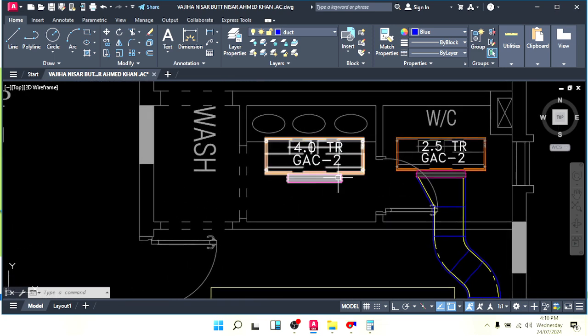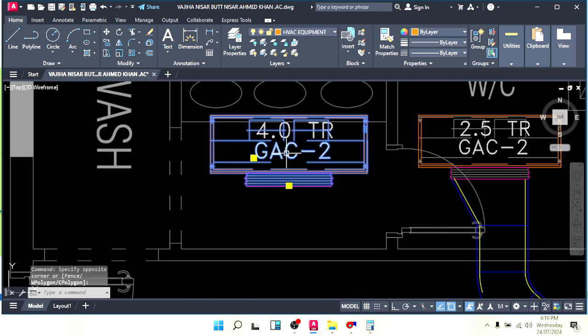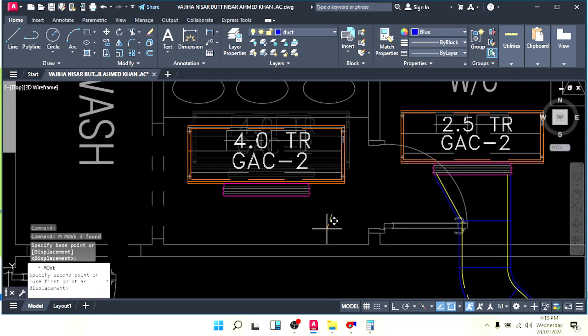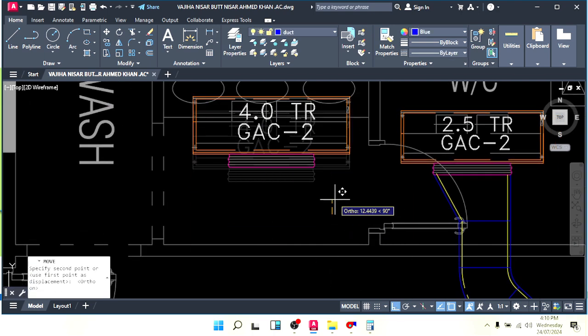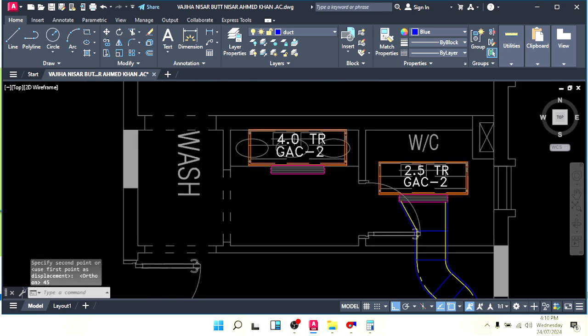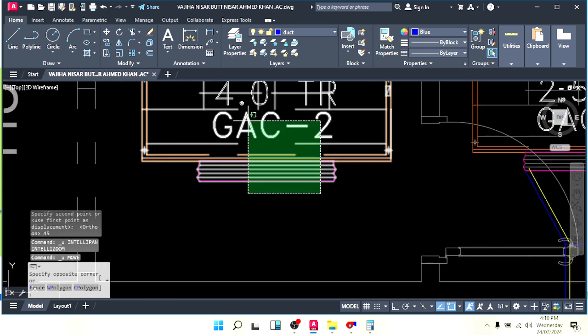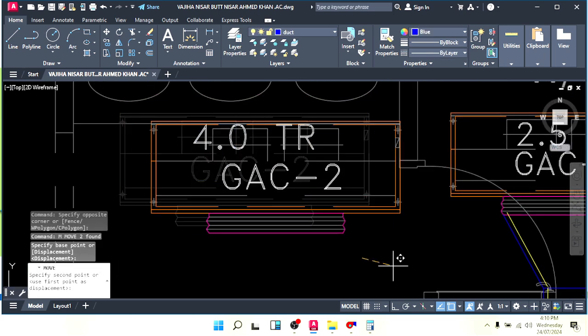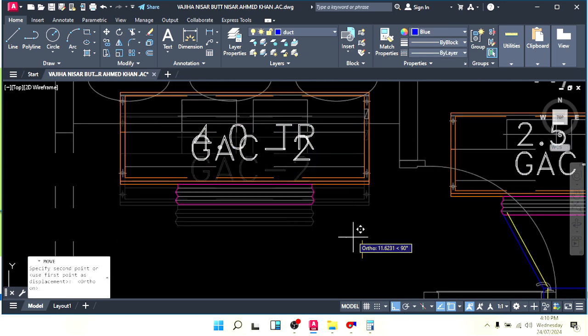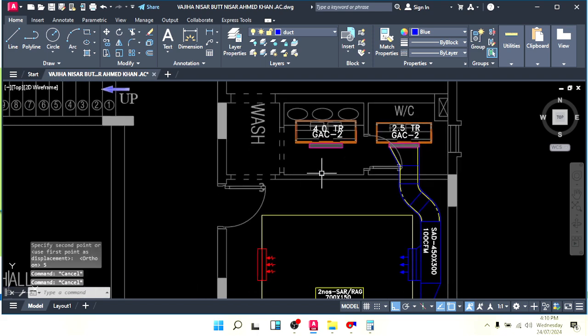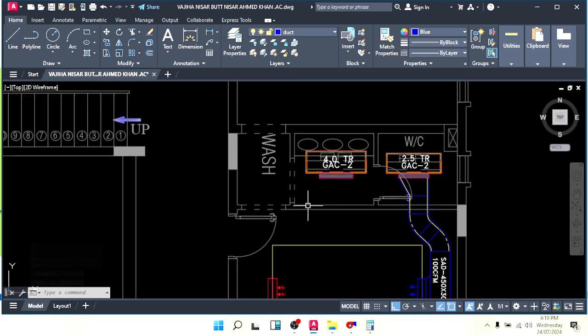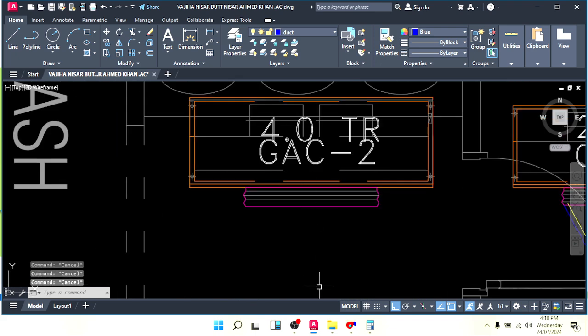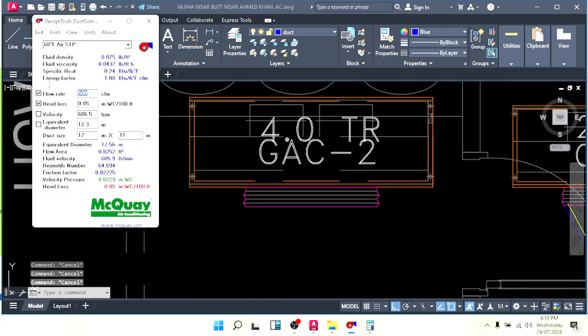Now let's draw the duct for this one. If I make it a little back more, because we have 40, so I keep 5 centi more, I take it back. 5 centi, go back, because I need elbow here, 90 elbow, so I just want more space in this part. Okay, now 4 ton. So 4 ton means 1600 cfm. Write down 1600 cfm.